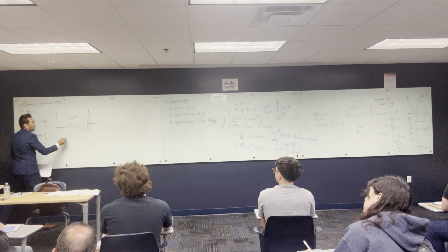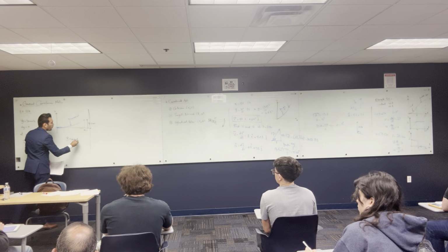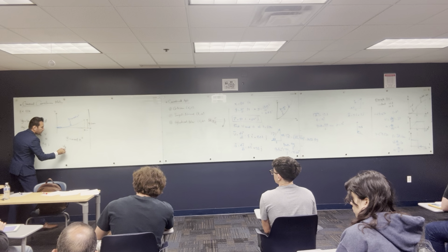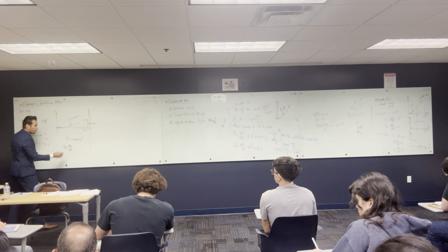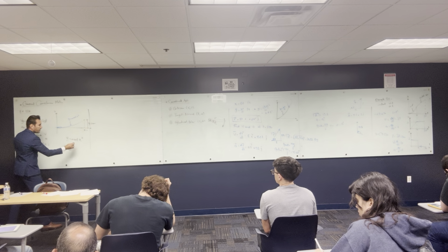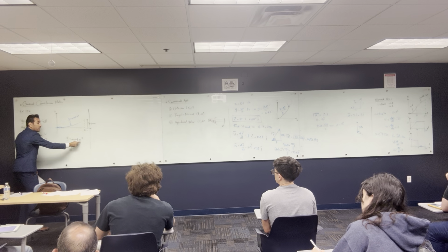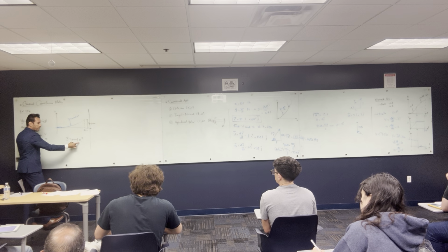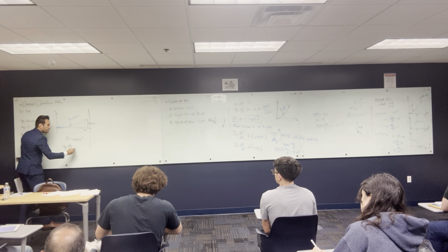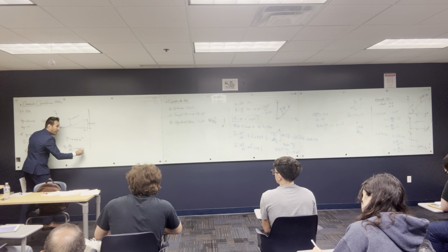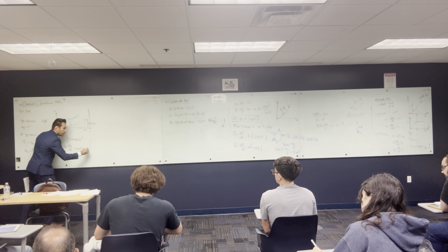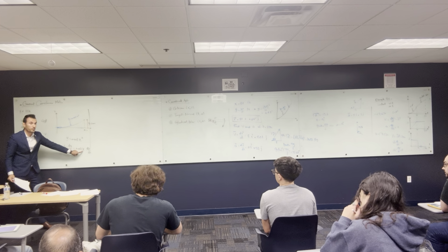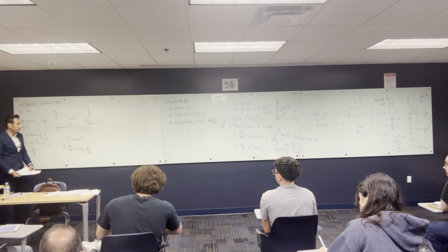If you have y is equal to 0.001 x squared, and you want to find the velocity Vy, so Vy is equal to dy/dt, right? So I have to differentiate this with respect to t. Can you guys differentiate this? By the way, this variable is x. This is going to be 0.002 multiplied by x, and here I should put dx/dt, because I'm not differentiating with respect to x, I'm differentiating with respect to t. So at the end I have to put dx/dt.